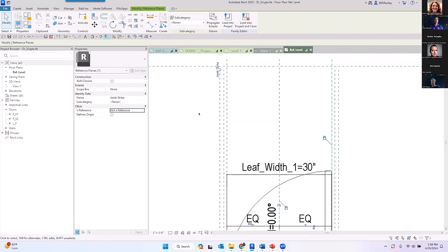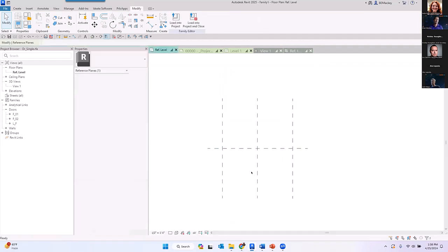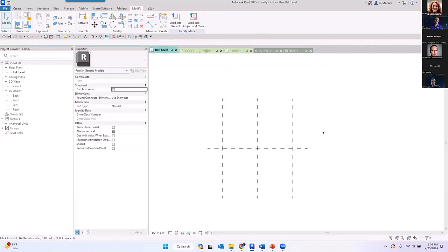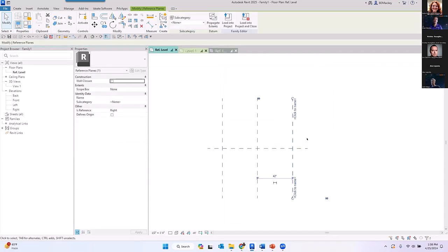It's like if you're trying to place a piece of casework in there or an HVAC unit, it'll snap to any strong or named reference planes like next to the wall or the other object, but it doesn't snap to those weak reference planes. So understanding that becomes critical as well. One of the other fun things about reference planes, besides those two things, is also the fact that there's directionality inside of there.